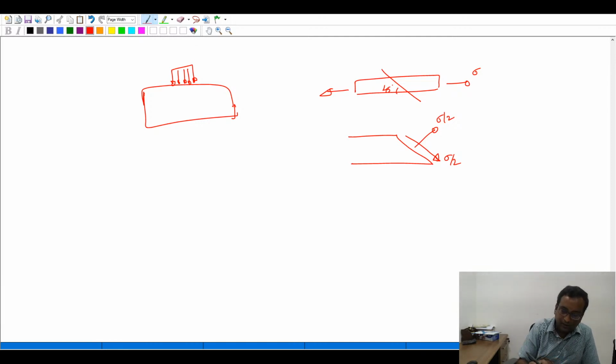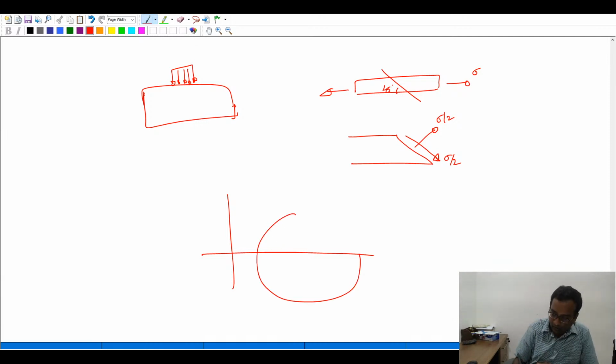For example, that's why in a Mohr circle, what happens? Only 2 points have only normal stresses, right? That is, the maximum and minimum principal stresses points have 0 shear stresses. All the other points have shear stresses in them. Okay, so basically that is the reason why only 2 planes have no shear stresses.